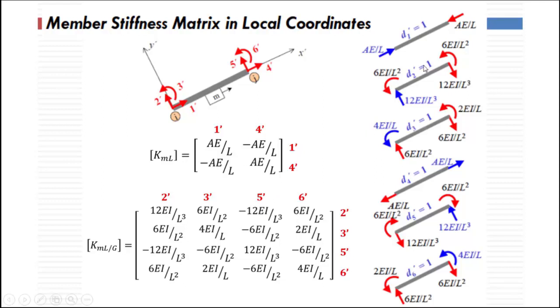All of them involve introducing a unit deformation along the designated freedom and then listing down the stiffnesses corresponding to those deformations. So now instead of two freedoms, vertical and rotational, per node, we now have three degrees of freedom for each joint or node. We have axial, in this case shear, and rotation. But it's basically just X, Y, and R, or rotation.